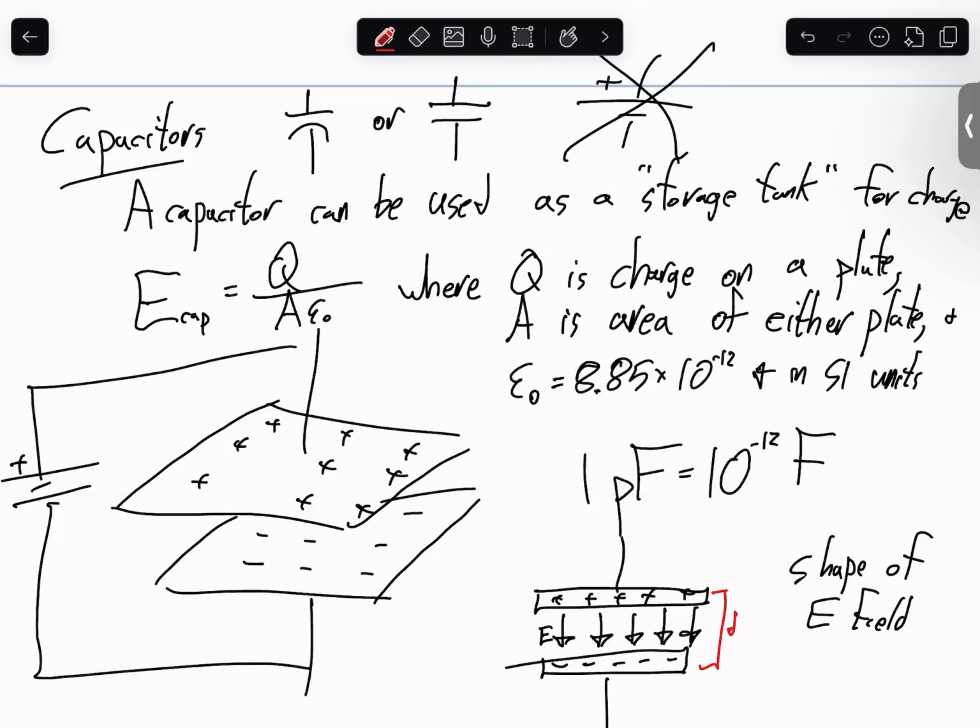If I attach the minus terminal here and the plus terminal here of the battery, this plate would get pluses, this plate would get minuses. So I rewrite it. There are some capacitors, polarized capacitors, electrolytic capacitors that have a material inside that can only be charged one way. If you put it backwards, they pop, they blow. So the battery looks like this force that rearranges. We're going to talk a lot about the rearrangement process. Keep asking about that. I'm going to try to explain that.